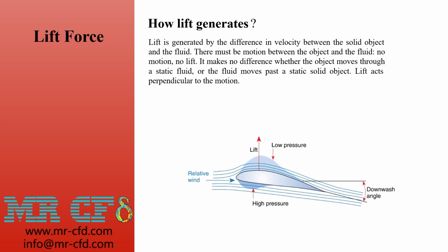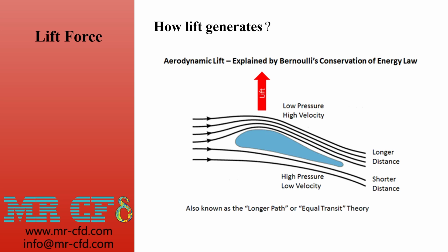Lift occurs when the flow of a gas is turned by a solid object. The flow is turned in one direction, and the lift is generated in the opposite direction, according to Newton's third law of action and reaction. Because air is a gas, its molecules are free to move about, and the solid surface can deflect a flow. For an airfoil, both the upper and lower surfaces contribute to the flow turning. Neglecting the upper surface's part in turning the flow leads to an incorrect theory of lift.